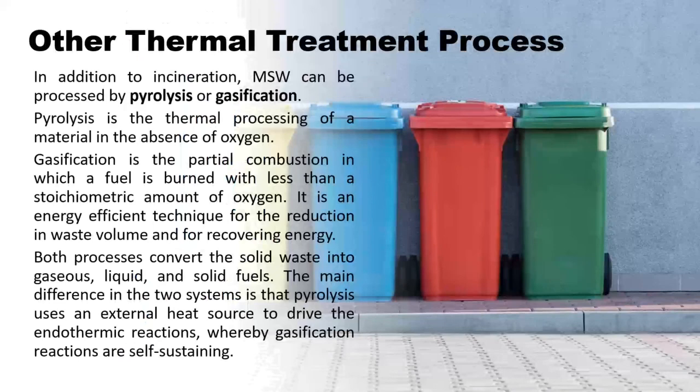Other thermal treatment processes: in addition to incineration, municipal solid waste can be processed by pyrolysis or gasification processes. Pyrolysis is the thermal processing of a material in the absence of oxygen. Gasification is the partial combustion in which a fuel is burned with less than a stoichiometric amount of oxygen.